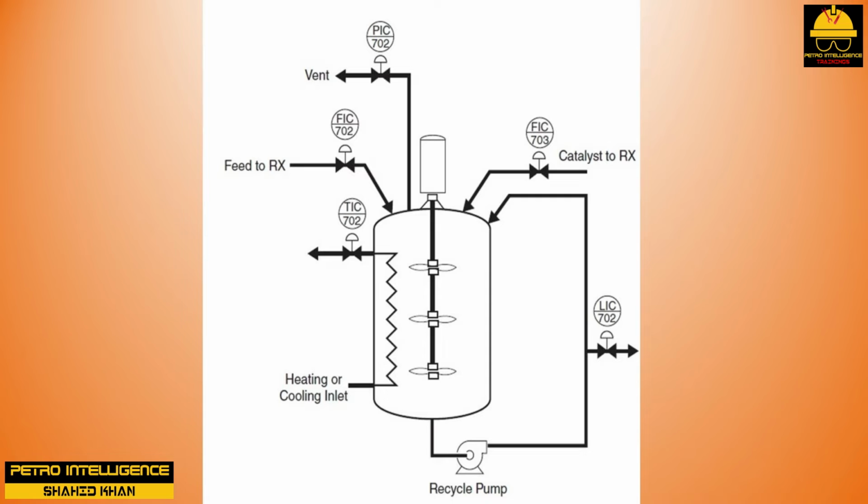Process variable alarms will be activated by analytical, composition, pressure, temperature, flow, level, and time variables. Rotational speed on the agitator may be fixed or variable. A series of interlocks, permissives, and alarms will engage during operation and will provide a support network for the technician. A series of process video trends will be displayed to track each of the critical variables. Samples are taken frequently to ensure product quality. Stirred reactors are connected to off-specification (off-spec) systems that allow flexibility in switching between prime and off-spec situations.